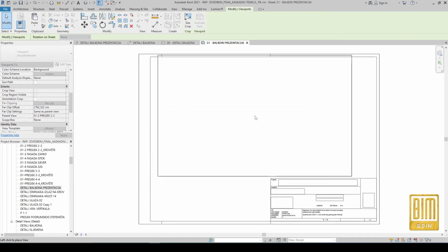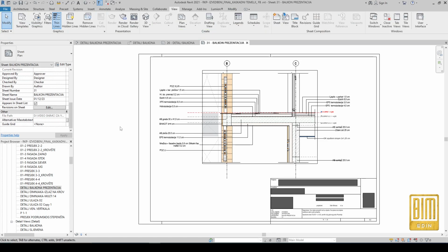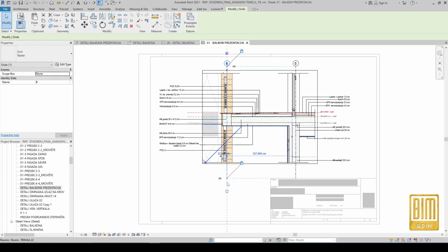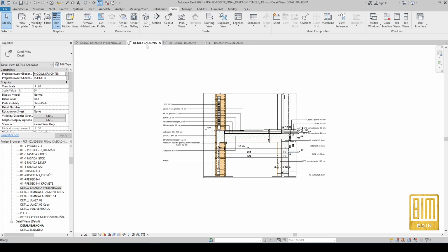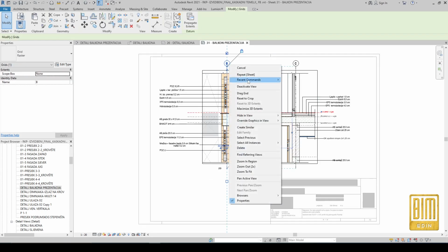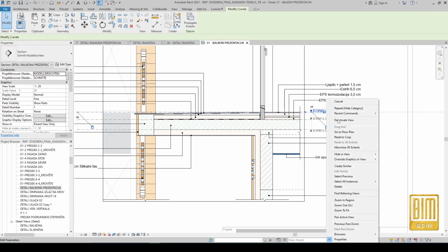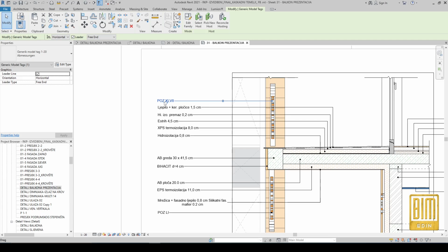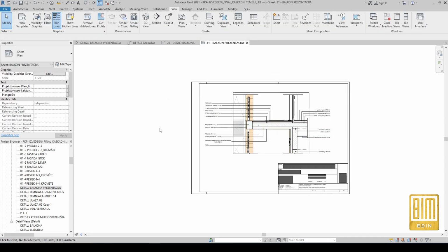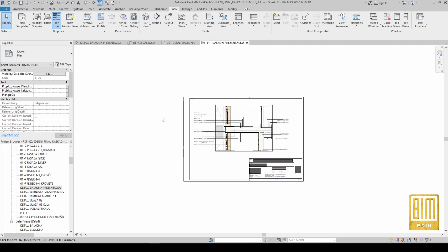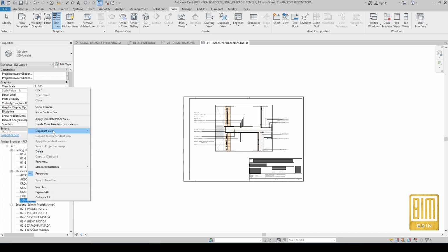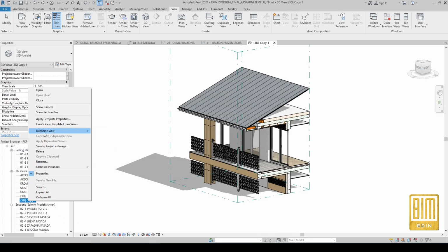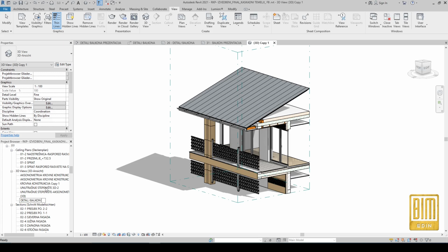And especially for this tutorial, let us repeat. First, you need to create fill regions. If you are going to use this method, you need to create fill regions, because when we change scale in the model directly, the scale of the fill patterns changes. They become smaller, invisible, and if you want to create good detailed presentations, you need to first create a fill region for every scale.